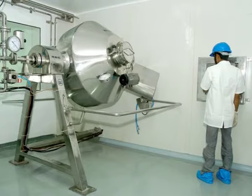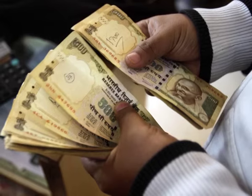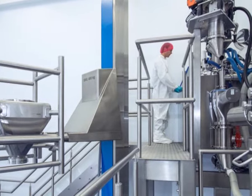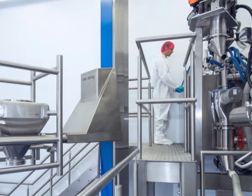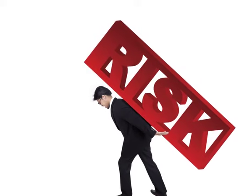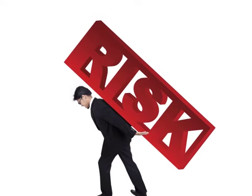A pilot plant allows investigation of a product and process on an intermediate scale before large amounts of money are committed to full-scale production. It is usually not possible to predict the effects of a many-fold increase in scale. It reduces the risk associated with the construction of a full-scale plant, and in the process less capital is required. Hope this lecture is enhancing your basics about the pilot plant, and now we will move on to the next module with more details on the pilot plant, and you will learn more interesting facts and details.